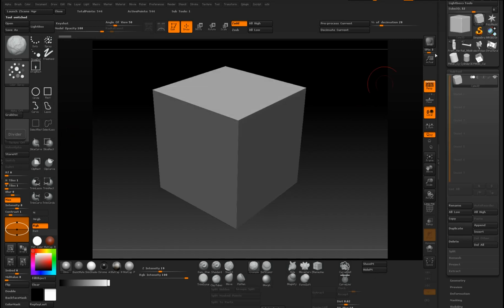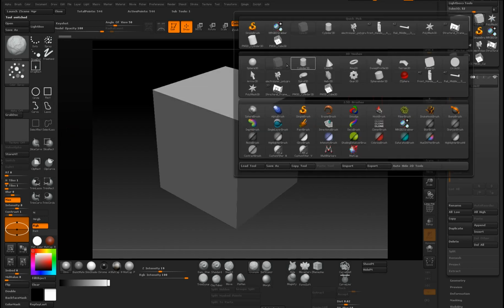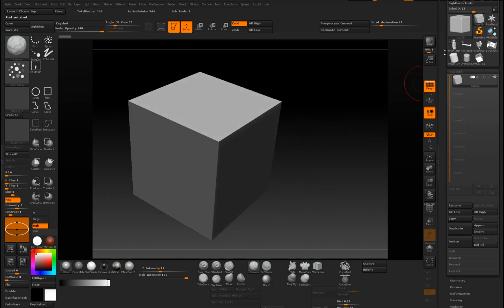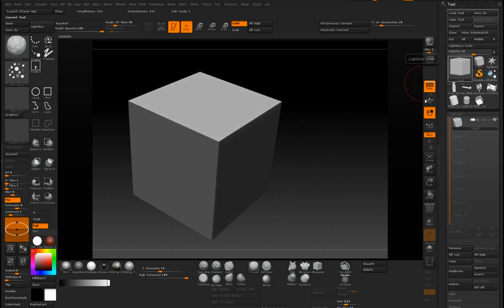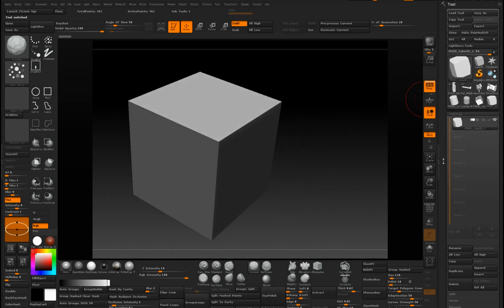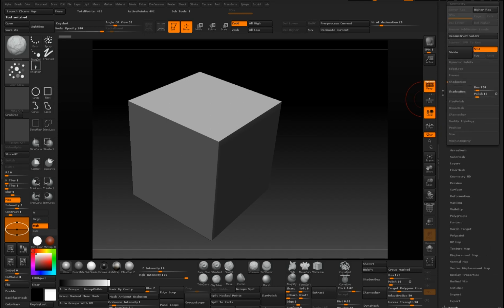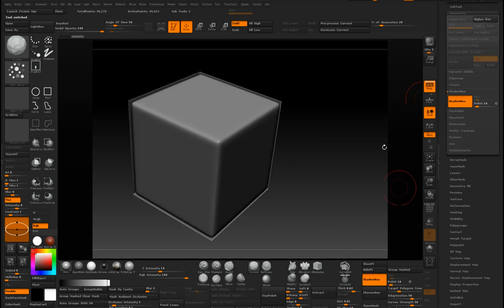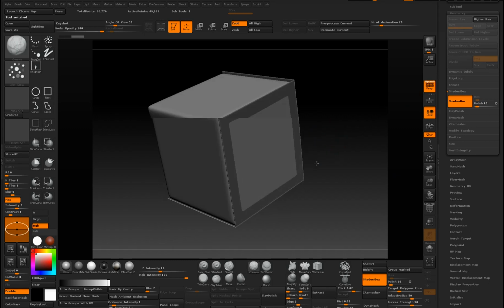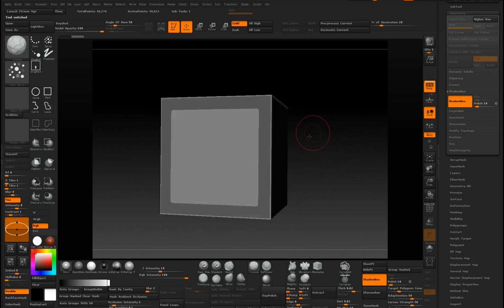But let's jump into it. So I've picked a primitive cube in ZBrush, and make it PolyMesh 3D. It will allow you to enter into the Shadowbox mode. I click the Shadowbox button, and now it kind of projected that cube on all the sides.